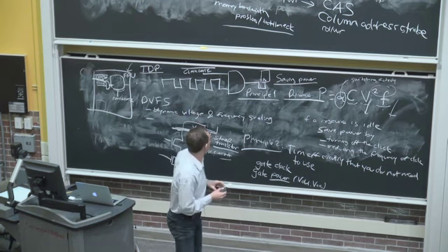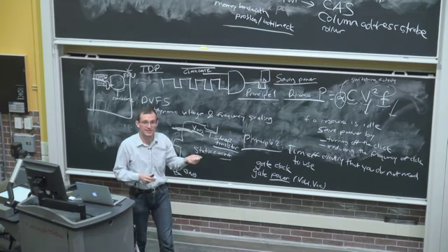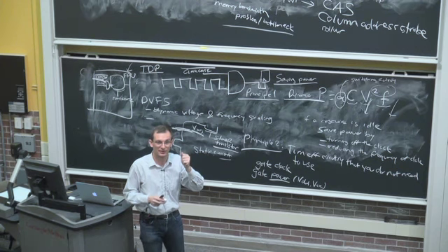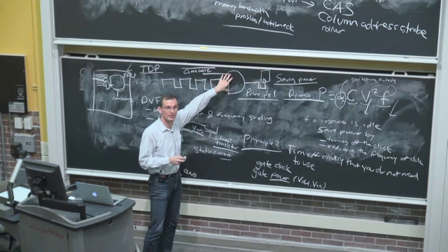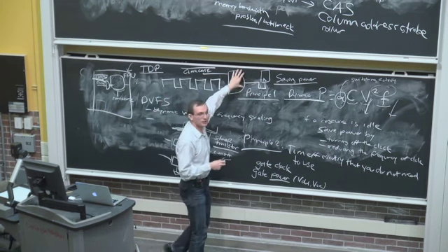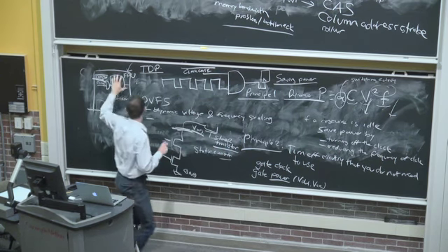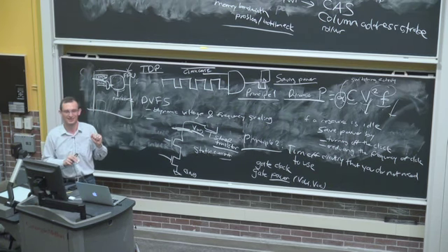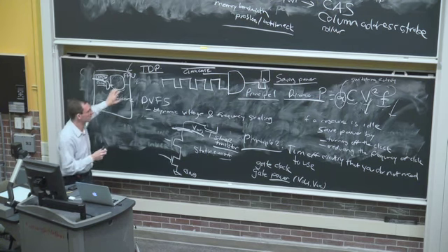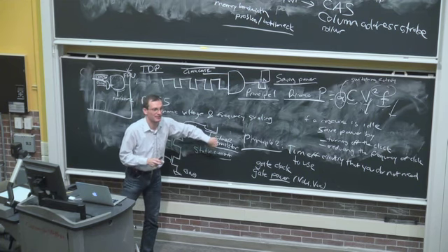I mean, there are other concerns, of course, right? Let's say you turn it off. There's always a latency to turn it back on. So you need to carefully consider the decision of when you turn off and when you turn on. Because let's say you turned off your floating point circuit, and one cycle later you get a floating point instruction. Well, you need to turn it back on now. But turning it back on, especially if you do power gating, takes time. It takes some number of cycles.